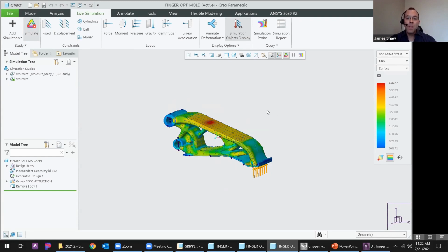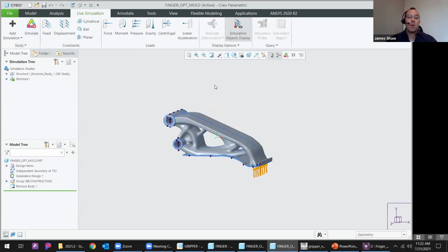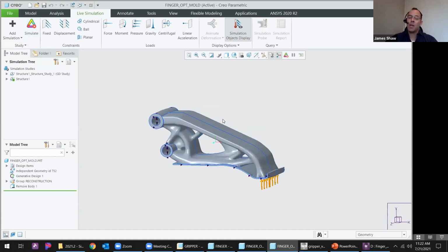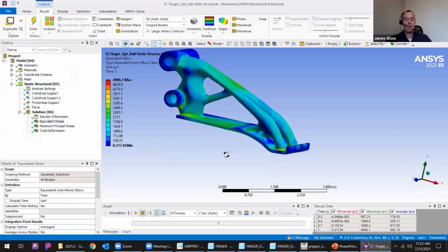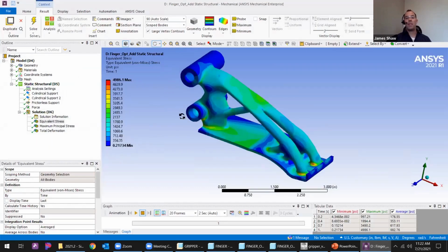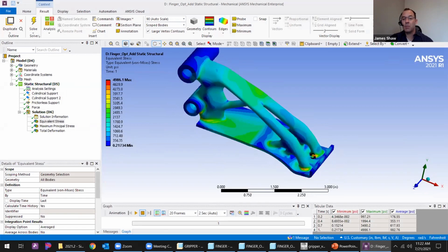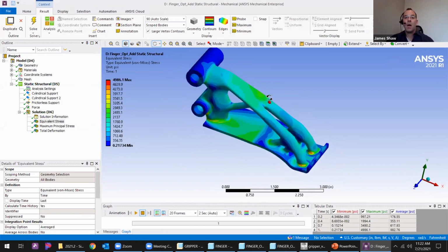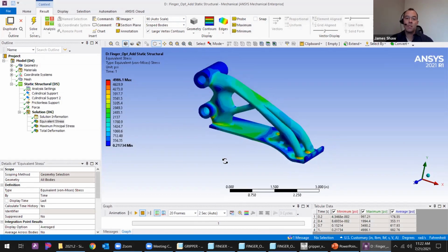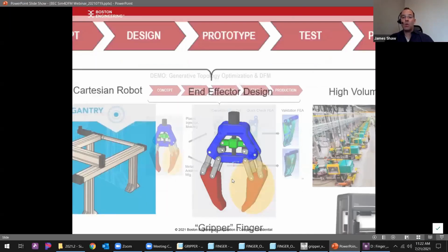even for a little laptop like this. Of course, if we needed to do a pre-validation, we would go right into ANSYS. So here would be a classic ANSYS Mechanical and Workbench, and this would be the same exact setup here: my cylindrical supports, and I'm adding my load. I'm going to look at a little bit more detail. I'm actually picking up some stress concentrations here that our quick tool did not pick up. So a full suite of tools, in this case Creo from PTC and also ANSYS, that are talking parametrically back and forth. So if we go back to the slides here, what just happened?